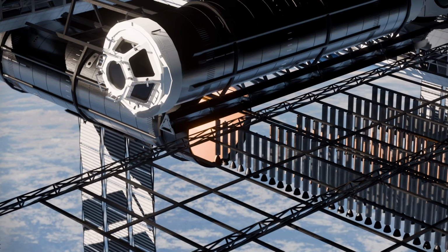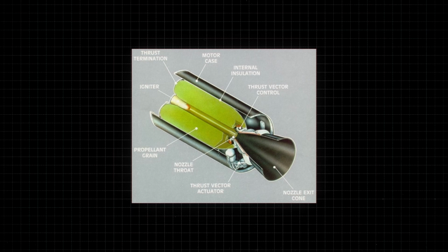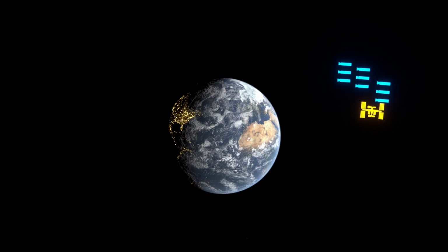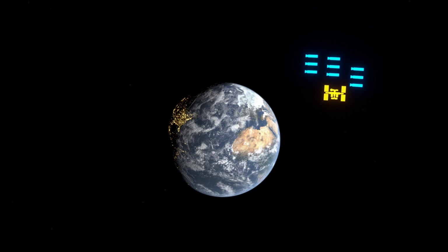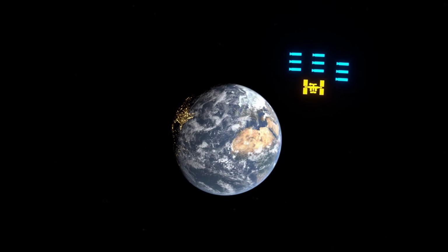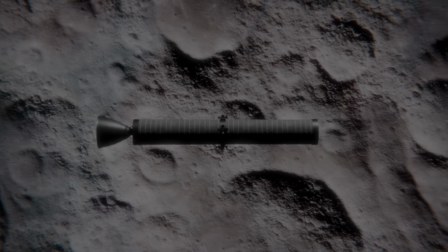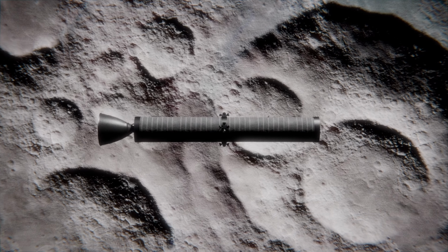The total rocket pod is 500 kilograms, full of propellant and fuel, but the dry mass, just the spent casing plus whatever payload it has, would have a total mass of 85 kilograms. So if the total useful mass delivered to orbit is arguably the full 85 kilograms, not just the 35 kilograms of flexible payload, then counting the spent casings as the true exported mass, at one pod every 3 minutes, that works out to about 1.7 tons per hour, or nearly 41 tons per day.